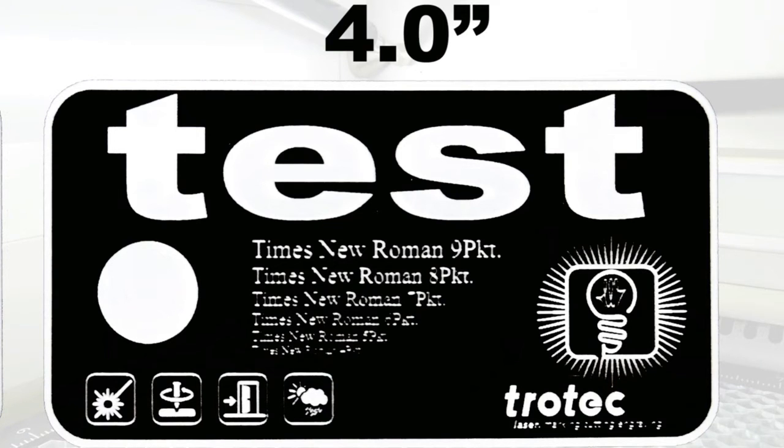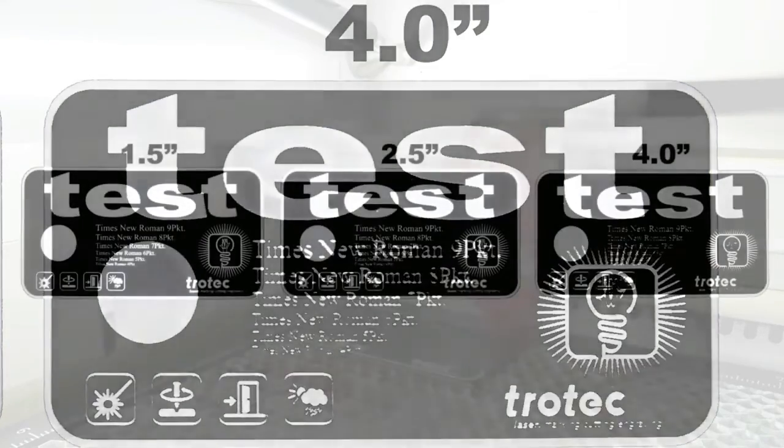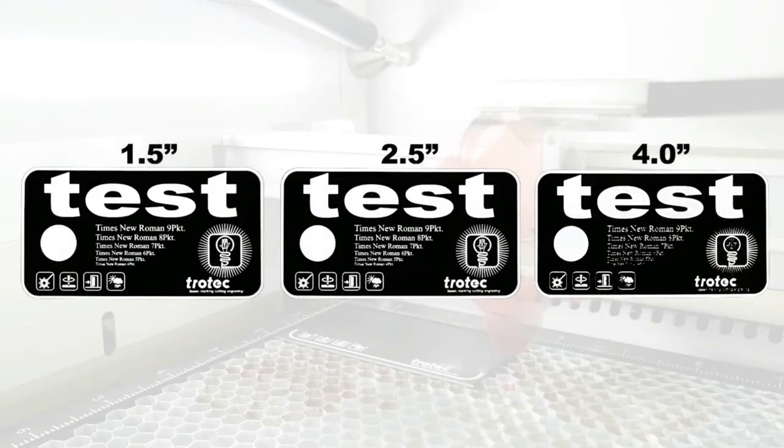Now we could reduce the speed significantly and you would see the vertical thinner lines. However, it would look bold and very undefined. The 2.5-inch lens is showing a result somewhere in the middle between the two. It looks technically speaking okay, but not as good as when using the 1.5-inch lens. And the conclusion is that the smaller the beam spot size is, the smaller and more detailed engraving we will get.